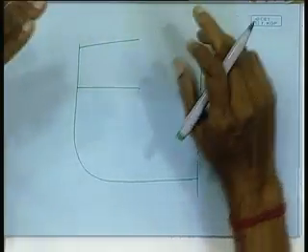I mean the construction also, the top deck will have a kind of a slope. This is not in the longitudinal plane, this is a transverse plane. Yes, but if it is sloped on both the sides, then that will resist the longitudinal bend. Okay, you mean to say that instead of having a flat plate, if it is a little curved, then obviously its section modulus increases. Fine, that it will contribute, definitely. Once the plate is flat, and if I give a little curvature to this, it has a much higher bending strength, stiffness. True. If that is so, then why is the lower deck flat?